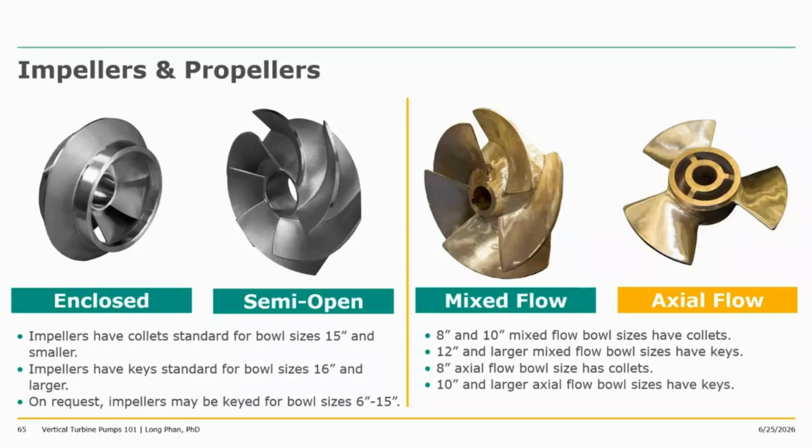The first two, enclosed and semi-open, have vanes that are designed and enclosed within a shroud. With the fully enclosed, both sides are closed; semi-open is one side closed, the other open. A mixed flow is really a balance. It's also an open impeller, but it's a more balanced design.